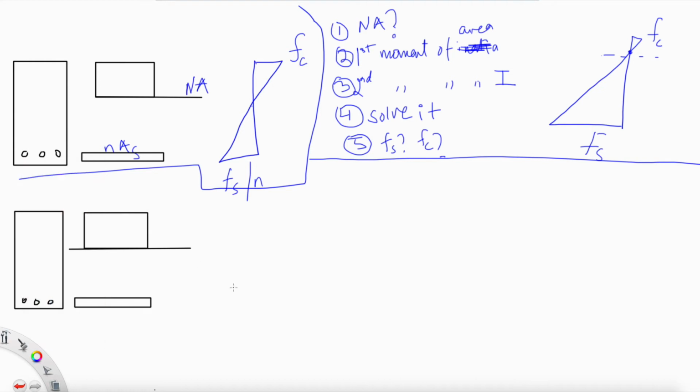Okay. We have a beam here. This beam actually has an area, assuming 3 inches square. I mean by the area is the steel area. 3 inches square, actually it is 3 bar 9. That's the number, diameter number 9, and it's three of it. Okay, the width of the beam is 12 inch. Okay, and its depth is 17 inch.